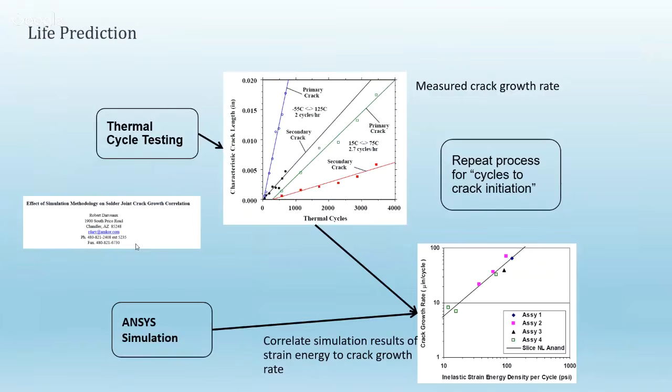From there, there's this process of predicting solder joint failure. These are often done by packaging companies. Companies are very interested in making sure that the chips, usually large BGA chips they produce, have a sufficient thermal cycling tolerance so that they don't break prematurely. The life prediction goes like this. You first conduct some thermal cycling. So you have a chip or a series of chips, and you do various thermal cycling for it, whether it's minus 55 to 125 or 15 to 75.